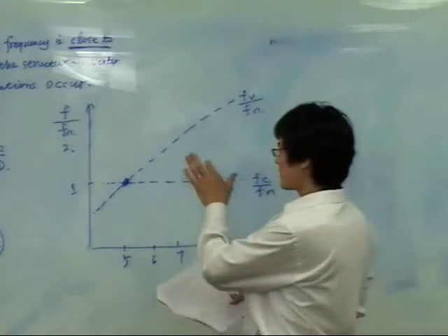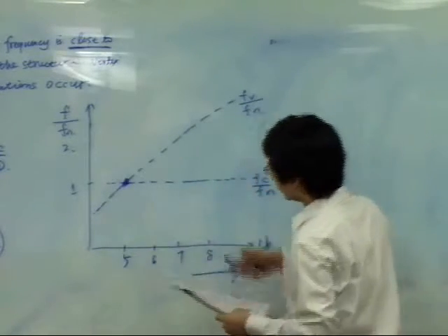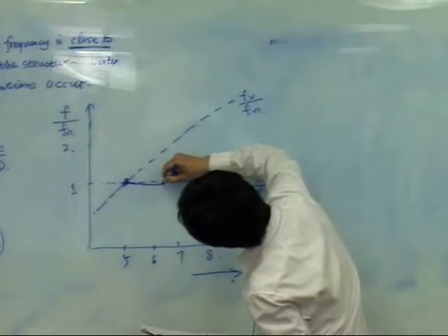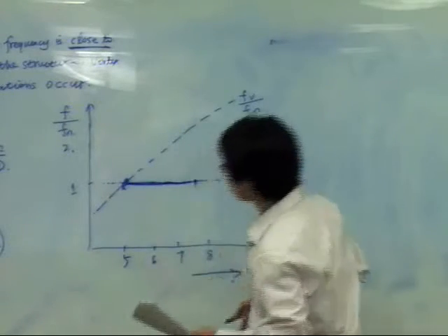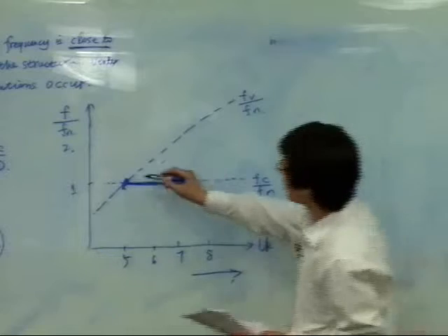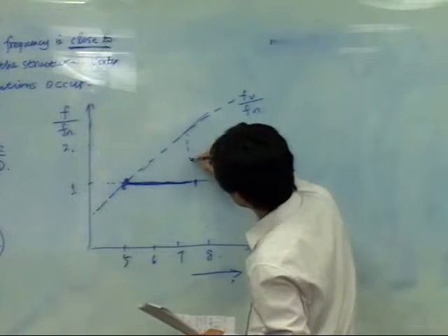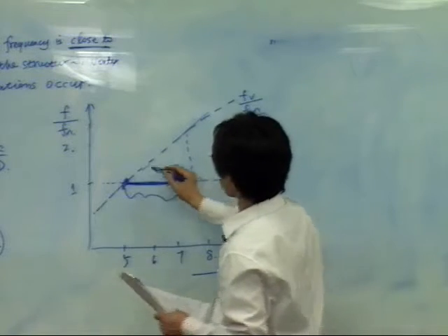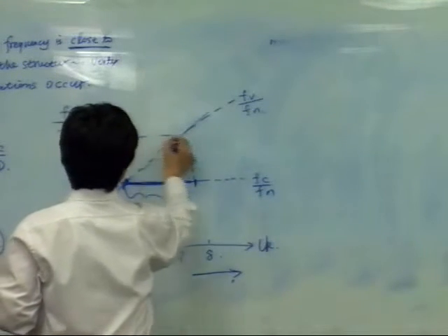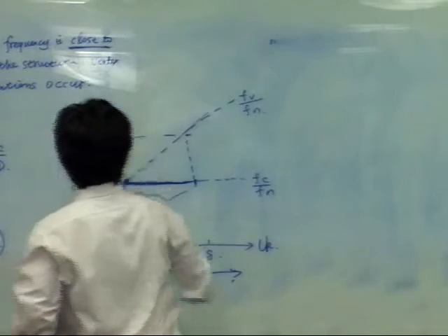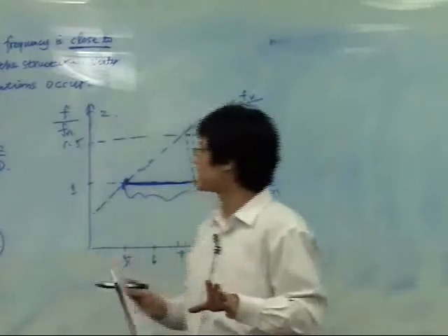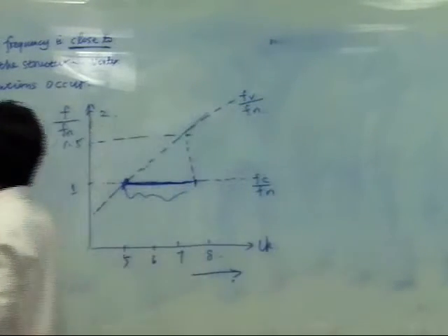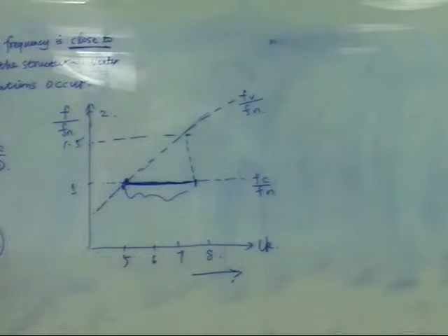But if we do observations for the VIV, we found that it's not a point. It's in a certain range. It should follow this line. However, we found that in this range, from about 1.5 to here, the vortex shedding frequency does not follow this definition, what it should be.